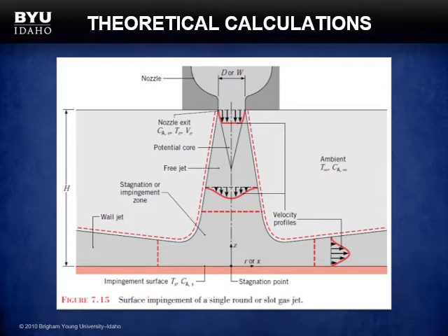We need to perform some theoretical calculations in order to compare with our experimental data. The distance from the glass to the heat gun must follow certain conditions. These are based on impinging jet equations for one circular nozzle, found in Chapter 7.7 of Fundamentals of Heat and Mass Transfer. By meeting these conditions, we can use Nusselt correlations for an impinging jet to find the heat transfer coefficient of the air blown by the heat gun. With this ambient heat transfer coefficient, we can then calculate the heat transfer. With the heat transfer, we are then able to calculate all of the temperatures.